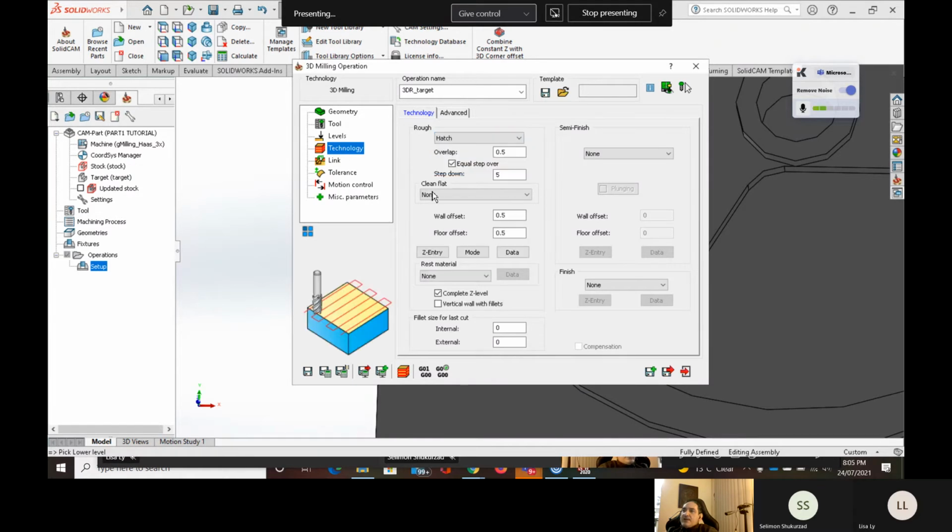Now I'm going to click on that. It's going to show me that this is the hatch operation. Another thing, the contour. The contour, as you can see, is not going to go outside the square. The hatch, the cutting tool will leave and come back. Okay, now that's the main difference between the contour and the hatch. I will try both of them.